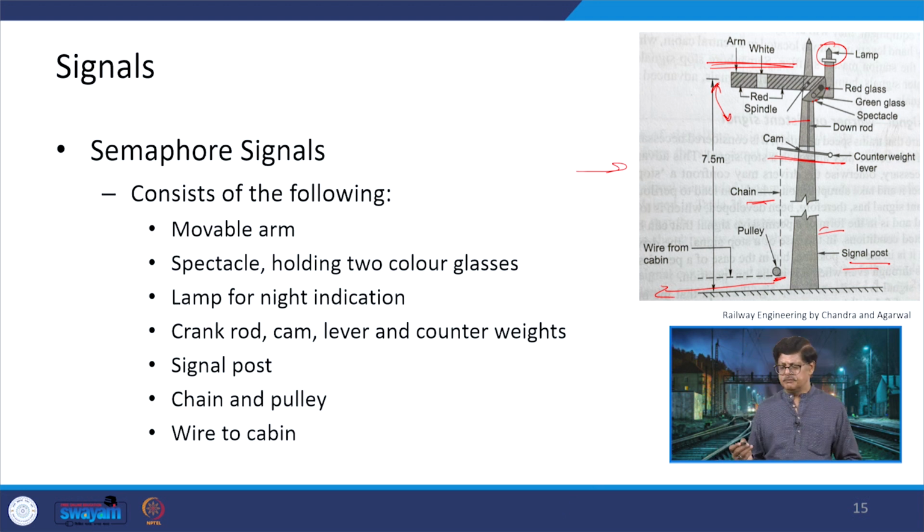So, sometimes you must have seen that there are certain levers which are provided at the side of the track. So, it means they can be set from that lever, that is a manual way in which it can be done at that particular location. So, when those levers are made either forward or backward, which is an interlocking system, then that will operate the connected signals to give information to the loco pilot what needs to be done.